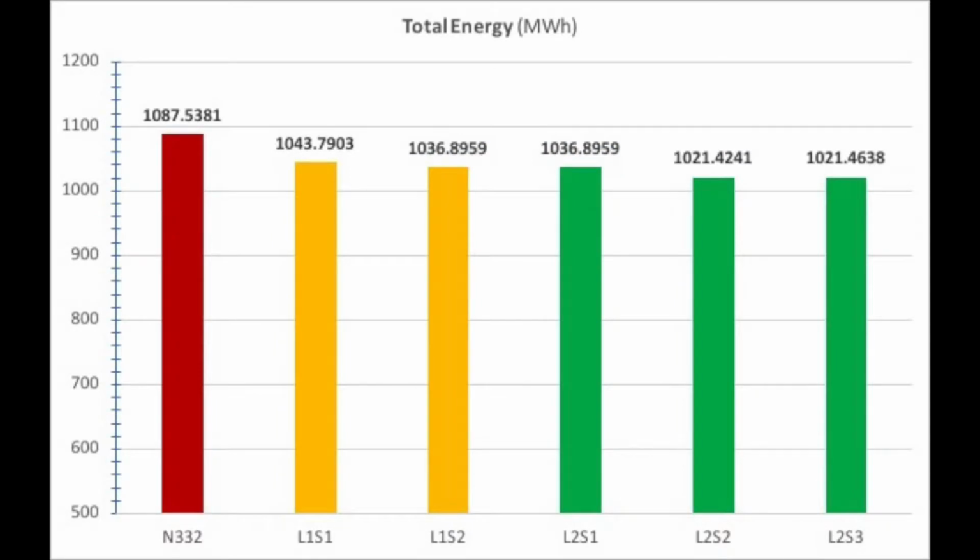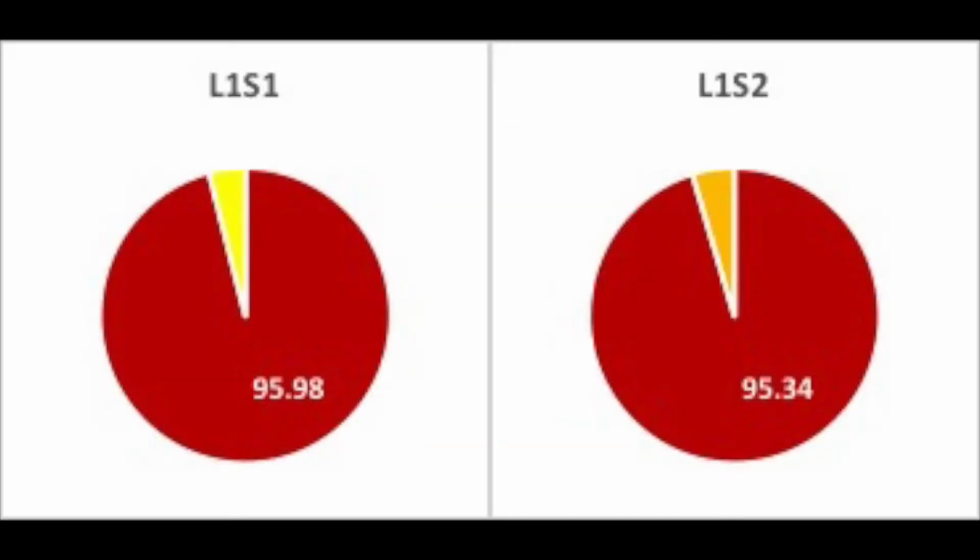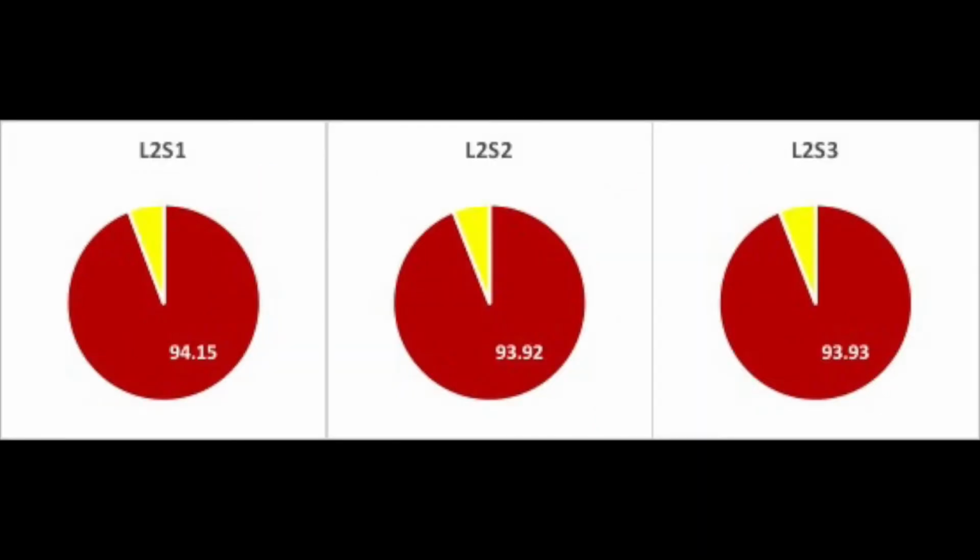When comparing the results of the total energy with the base case, some savings can be found. The savings are not significant as the main load in buildings for such cities is the heating load. When comparing the scenarios of the first location, energy use is almost 95% of the base case. The scenarios utilizing the core and with wind catchers working as intakes and exhausts yielded the least energy at 93.9% of the base case.